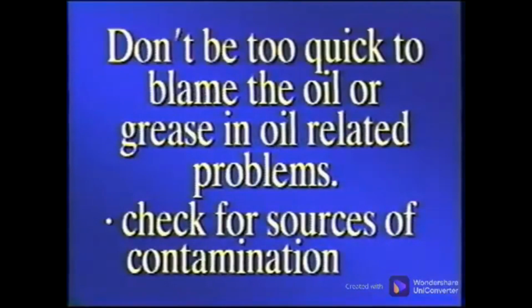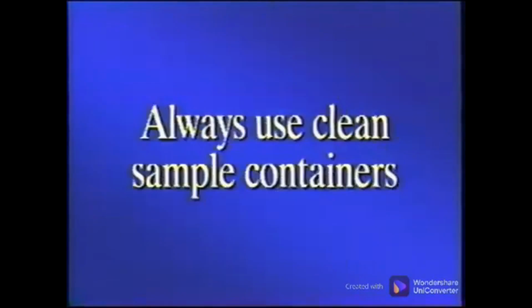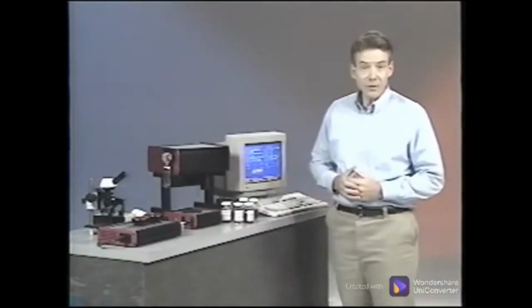Do not be too quick to blame the oil or grease in an oil-related problem. Look for outside sources of contamination and adverse operating conditions. Always use clean sample containers. Resample to ensure a representative sample. These troubleshooting tips seem obvious, but are sometimes automatically ruled out because they're obscured by the pressures of providing a fix to the current problem. While many areas have been covered, we've only highlighted the most common oil analysis practices and characteristics. We realize that unique design and applications necessitate special considerations for oil analysis programs.